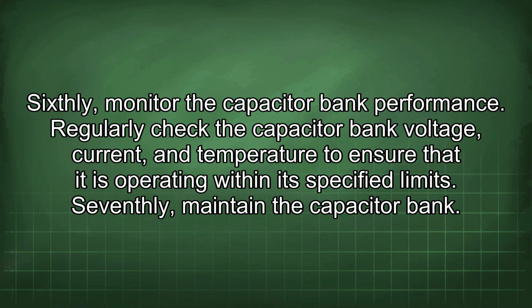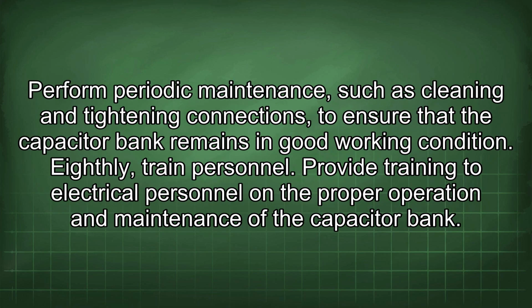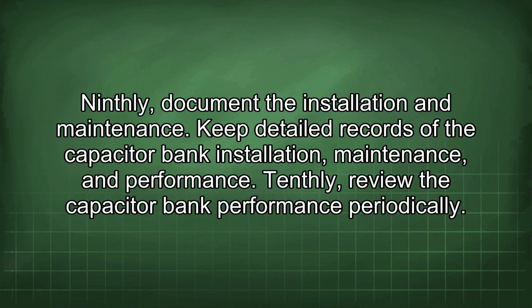Seventhly, maintain the capacitor bank. Perform periodic maintenance such as cleaning and tightening connections to ensure that the capacitor bank remains in good working condition. Eighthly, train personnel. Provide training to electrical personnel on the proper operation and maintenance of the capacitor bank. Ninthly, document the installation and maintenance. Keep detailed records of the capacitor bank installation, maintenance, and performance.